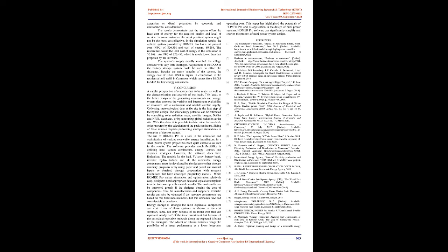The mini-hydropower interconnects with the PV solar system. The DC bus voltage is 1.2 kV, which is converted to 400 V, 3-phase, 4-wire by the converter for connection to the AC bus. The local community is powered from the AC bus. Figure 9 shows the simulation result.